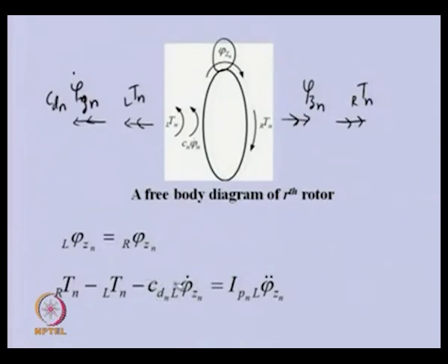Now, we can rearrange this equation. Because in this particular case we are dealing with, let us say, free vibration, whatever the torque there is will have some amplitude. This amplitude is basically a complex amplitude, and the frequency of that particular torque is equal to one of the natural frequencies, the torsional natural frequencies of the system.